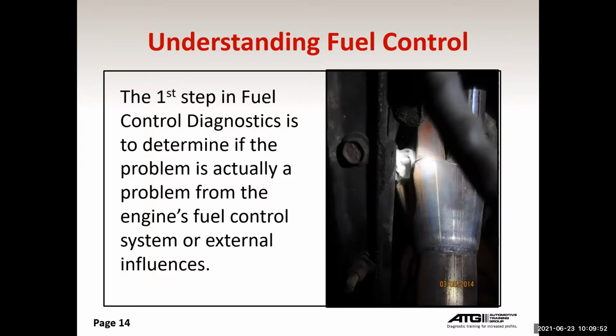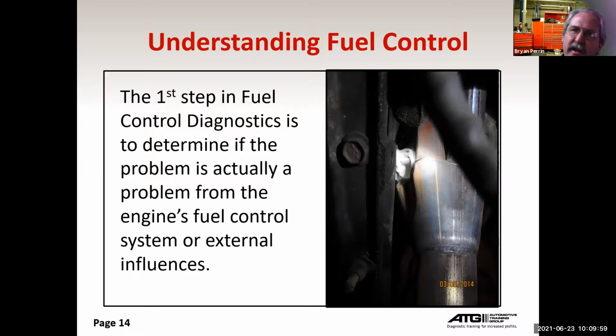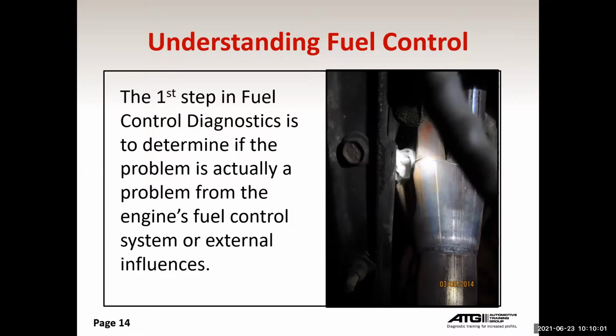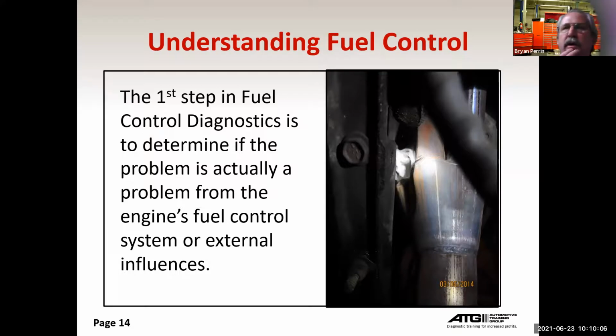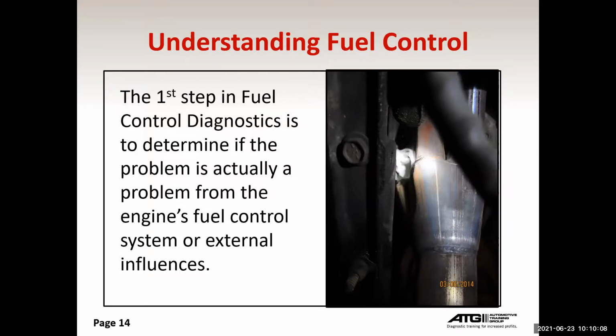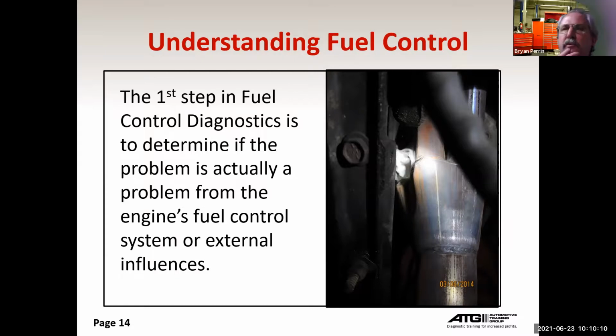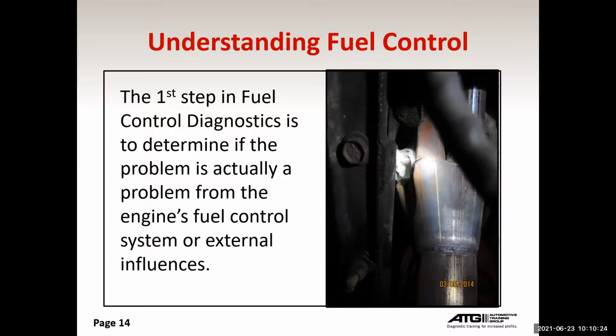Brian, yes. If it's a very small hole, can we just solder it rather than weld it? Soldering rather than welding? No, you can't solder it. The heat, first of all, is much hotter than what the solder can take. You just liquefy the solder, and solder doesn't really join things together the way welding does. Solder goes on top of where weld goes in. With weld, you're actually taking the material from each side and bringing it together.